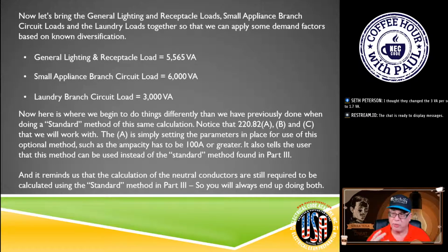At this stage, if we were doing the standard method, we would apply some demand factors in 220.42. But we're already going to get some good benefits here by using the optional method. There are some caveats: to use the optional method, the overall result has to be 100 amperes or greater. If it is less than 100 amps, then you have to shift to the standard method, which is part 3.